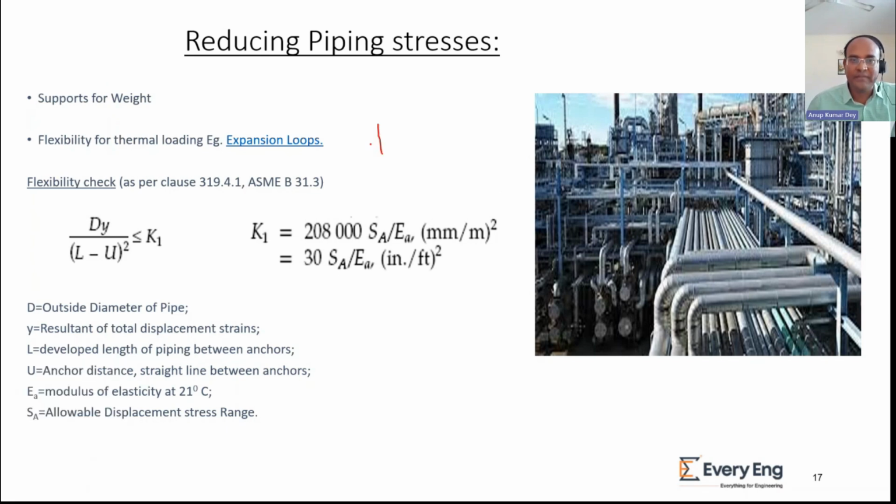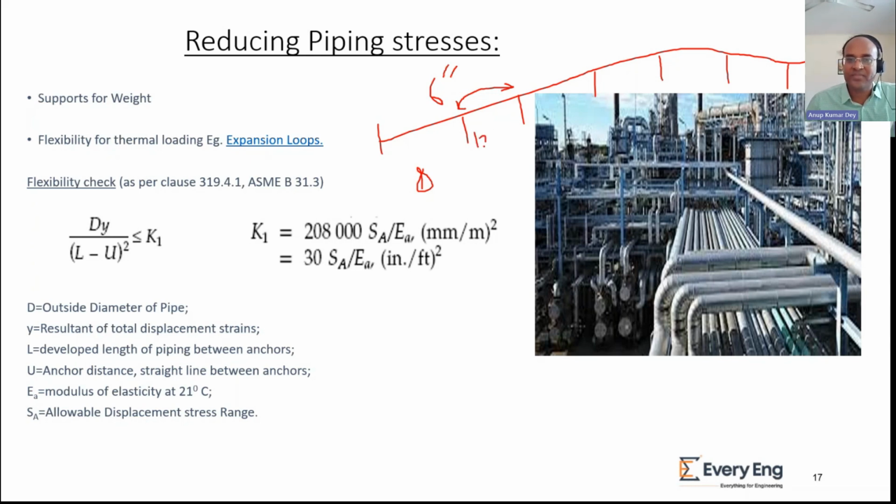Let's assume this is a pipe. It is running for a long run, and let's assume this is a 6-inch pipe for which the span is around 8 meters. So every 8 meters we have to provide supports so that it does not cause failure or unacceptable sagging. But due to certain reasons, if your piping designer could not find a structure during layout and they provided the support at 12-meter distance,